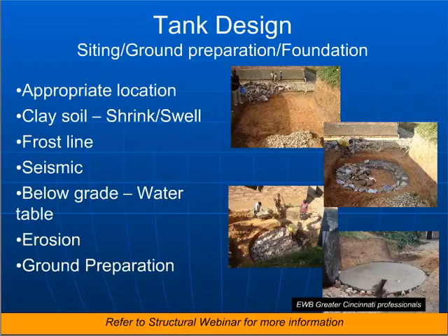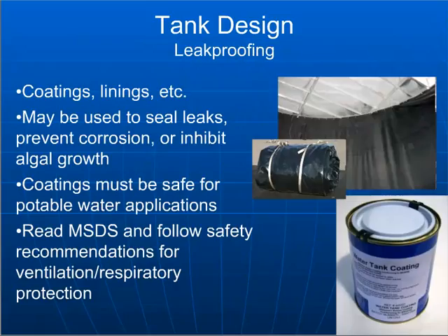Other issues, if you're encountering any type of clay soil, making sure that you provided an adequate base for the tank, and also making sure that you've made provisions for any erosion issues that might occur. So if you do get either overflow coming out of the tank or stormwater runoff that may be moving through the area, just making sure that that's not going to undermine the foundation or cause any other problems.